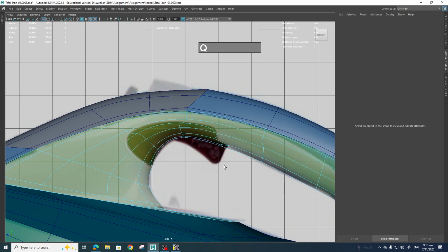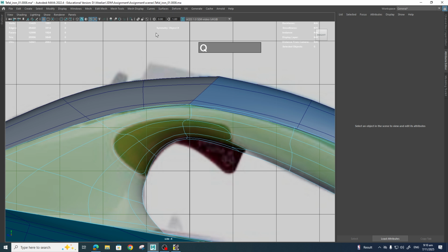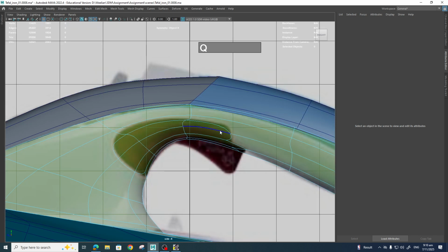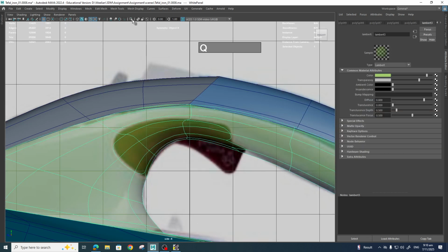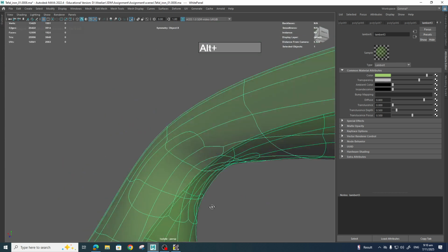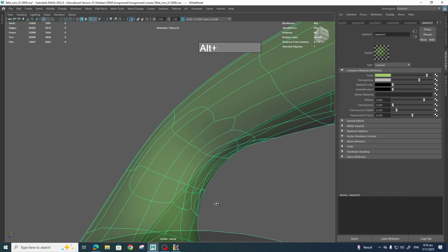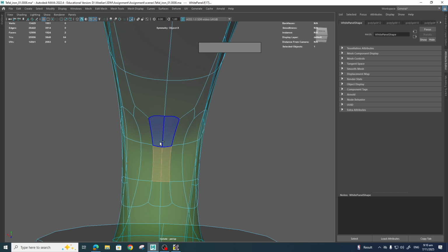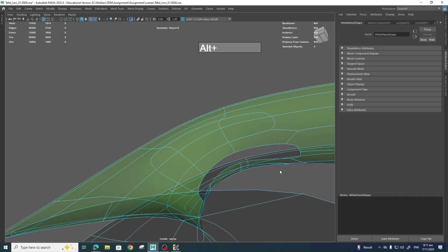But let's go to selection and isolate this piece. Okay, let me undo the isolate, because we are in component mode. We have to be in object mode to isolate this. Then we're going to check the cuts are correct on the other side as well. So the faces here, I can select them and delete them to create a slot for the trigger.